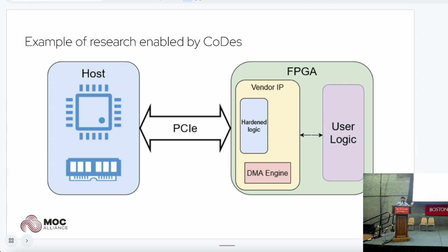The host is running some custom driver to support the PCI communication, which is specific to this FPGA device, because the file and the vendor-provided IP core differ from one vendor to another and even from one device family to another. So there's a lot of device-specific data that needs to be captured by this driver. Unfortunately, there's not a lot of upstream support in maintaining these drivers.